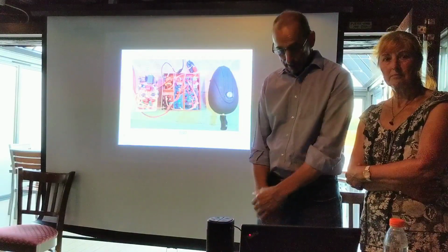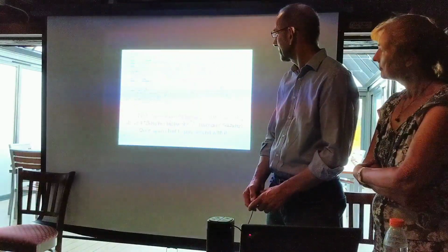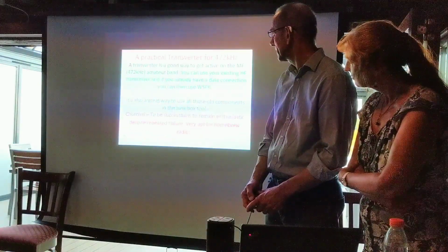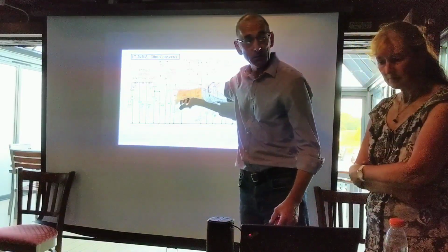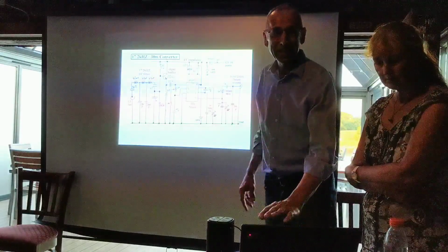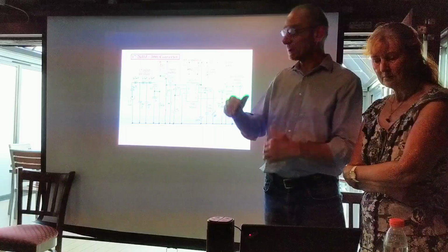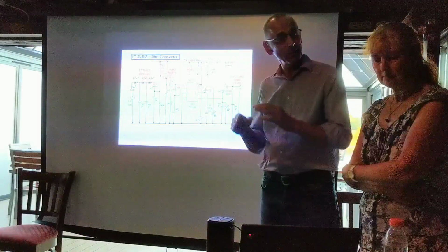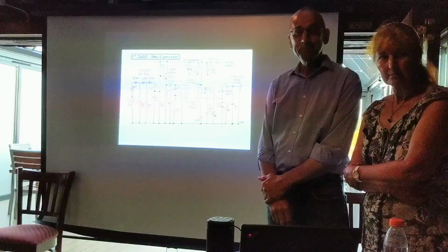I see, yes. And if we whiz back to that, back to the dark ages somewhere, you'll notice here it's actually got a pot you can put on it to balance it up. So if you're getting anything out of any of the 2 original frequencies, the local oscillator or the input, you can adjust that pot to balance it up, so nothing comes out apart from the difference product and the sum product.